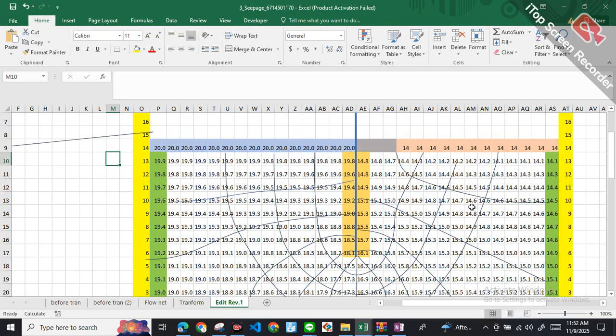Next, we're going to draw the flow lines. The flow lines are basically perpendicular to your equipotential lines. Just try to make it perpendicular like this, with a little twists and turns, and you can just draw it. You want to focus much on this part. So this is how basically you can draw your equipotential lines and flow lines.